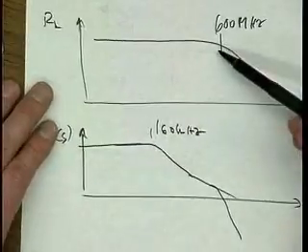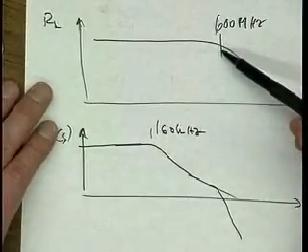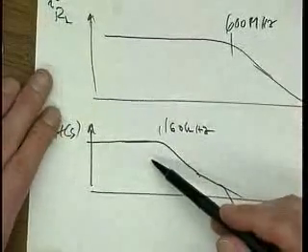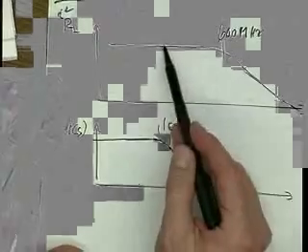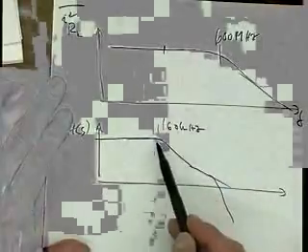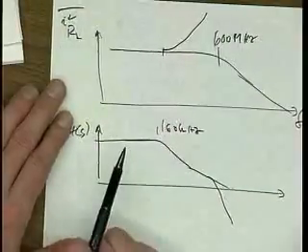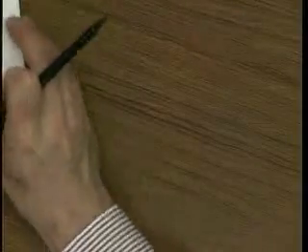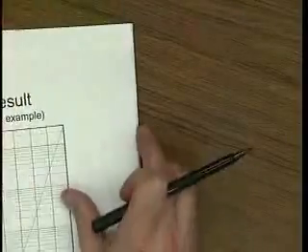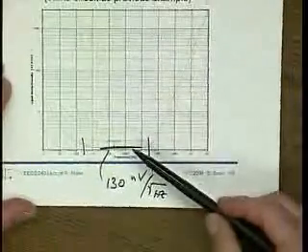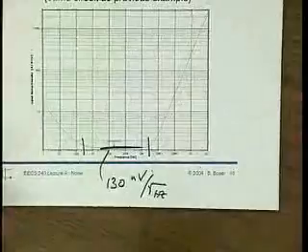Well, if I divide this noise by this here, then starting here, because what I'm dividing by decreases, this thing must go up. So input referred noise, in general, at high frequency, if we have a physically correct model, a situation that could actually exist, always blows up.